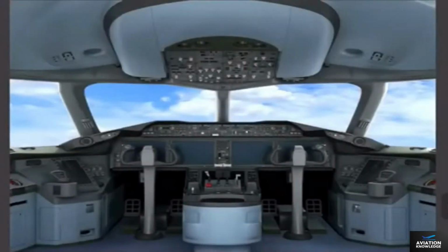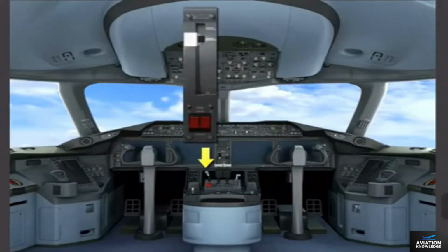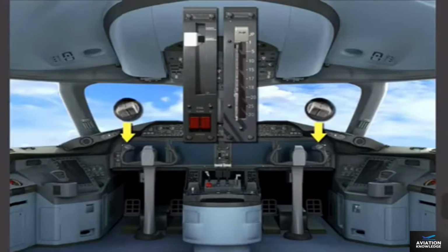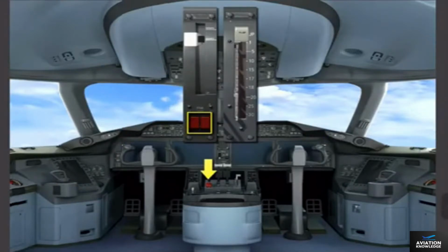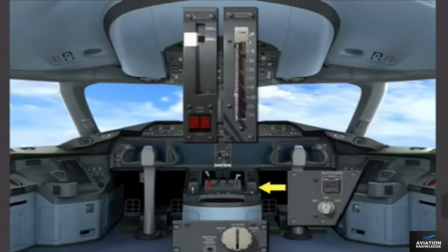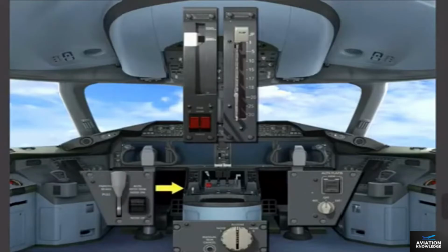The pilot controls consist of 2 control columns, 2 control wheels, 2 pairs of rudder pedals, the speed brake lever, the flap lever, control wheel pitch trim switches, stabilizer cutout switches, rudder trim selector, alternate flap switches, and alternate pitch trim switches.